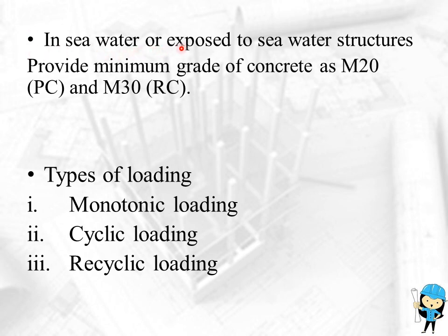For structures exposed to seawater, provide minimum grade of concrete as M20 for plain concrete and M30 for reinforced concrete.